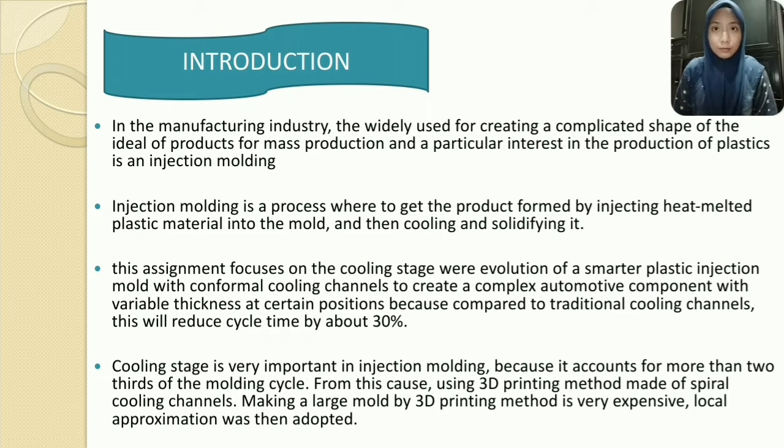In injection molding, the cooling stage is very important because it accounts for more than 2/3 of the molding cycle. Using a 3D printed mold made with spiral cooling channel, making a large mold by 3D printing is very expensive.